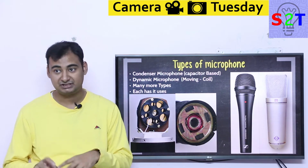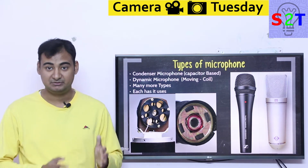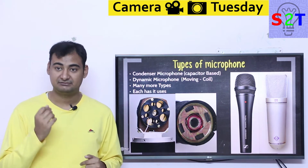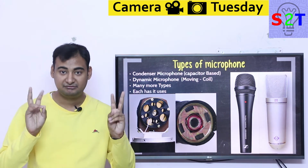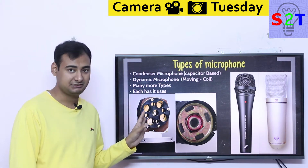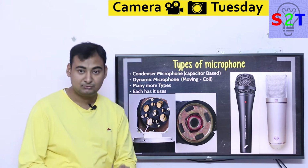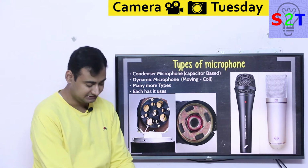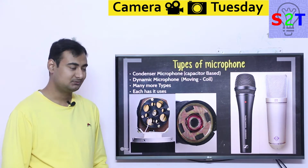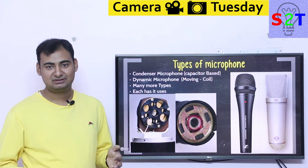Now that signal can be voltage, sometimes it can be capacitance itself. Other people use other things. Basically that's what's changing, and that is why a condenser microphone requires a voltage. You must have heard of phantom power, 24 volts, 48 volts. That's there to charge it. That's why you can have a small portable recorder that can power this one, the Zoom H1 can, but its bigger brother can too, because even though it has only 4 AA batteries, it does not need to do too much.